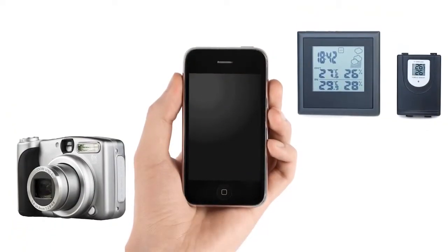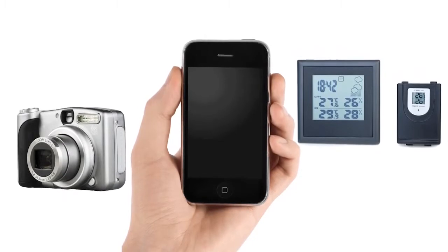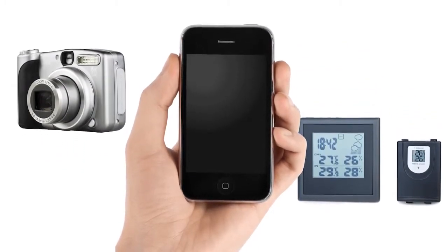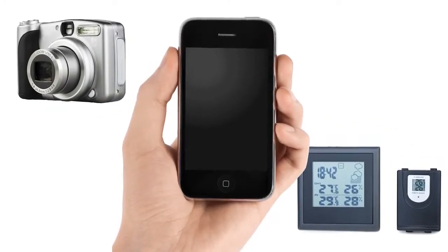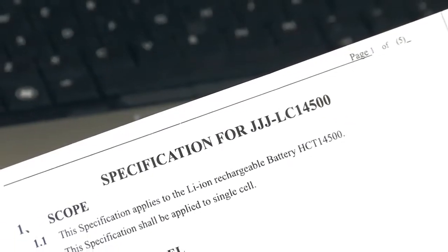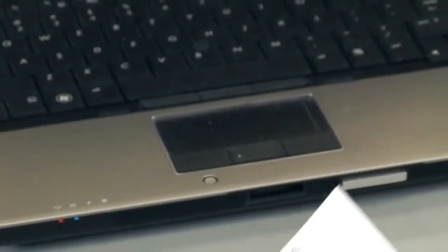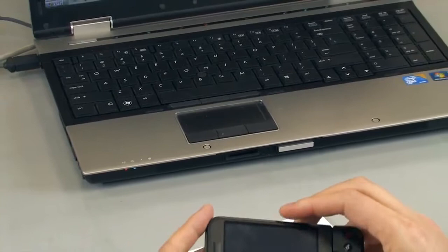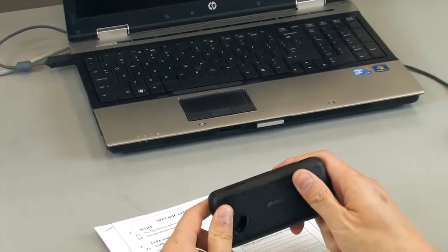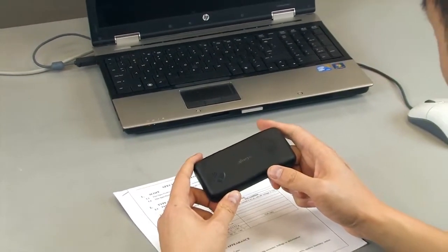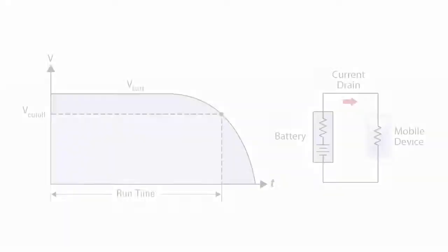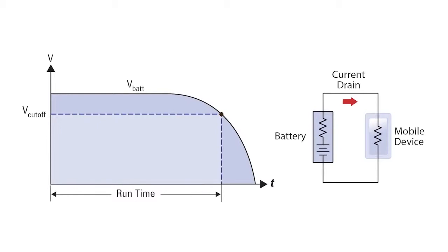Longer battery life is important for mobile phones and other mobile devices. A key part of determining a mobile device's runtime is validating the battery's capacity and energy ratings. If you determine a device's runtime based solely on a manufacturer's datasheet, without validating the battery's ratings, your results are likely to be inaccurate. The stated capacity is often based on ideal conditions and represents the maximum charge you might obtain from the battery. Actual capacity will usually end up being less when you verify it in your application.